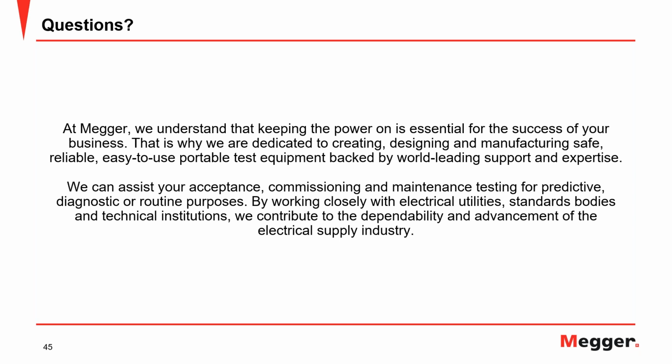Right. Thank you, Diego. Next question is for Sanket. Sanket, how is it recommended to obtain the temperature of the OIP bushings? So we assume that the temperature of the bushing is somewhere in between the ambient temperature and the top oil temperature. To be precise, you have to take the average of the ambient and the top oil temperature of the transformer.